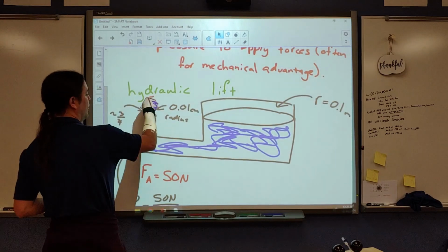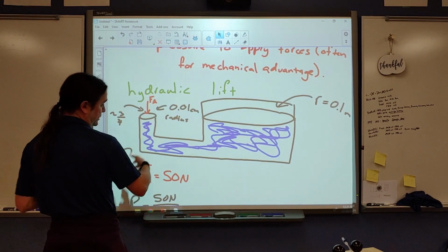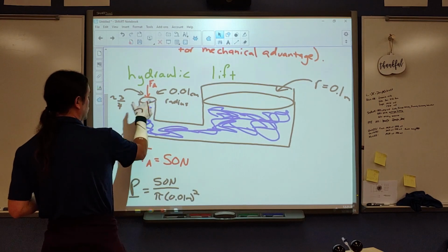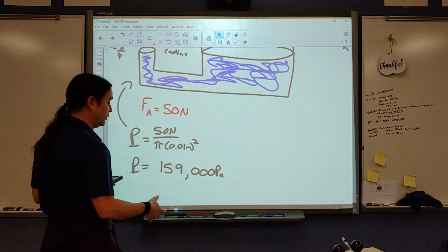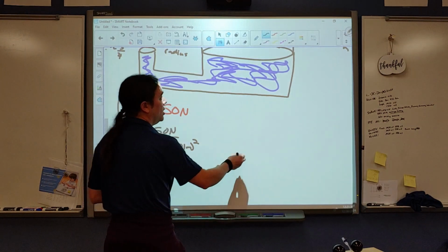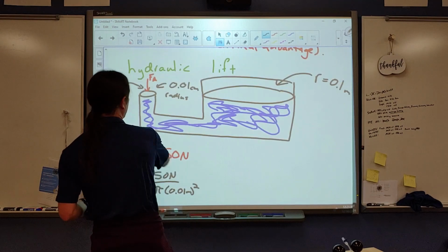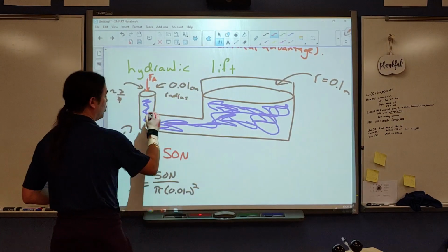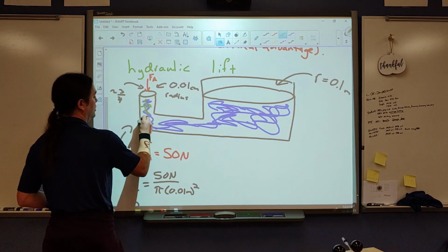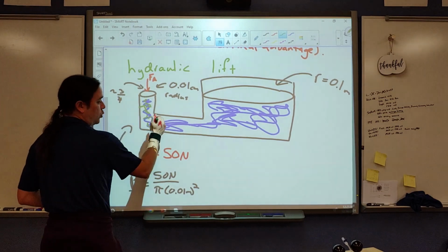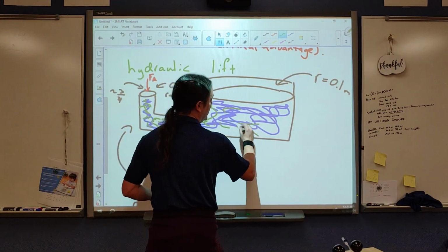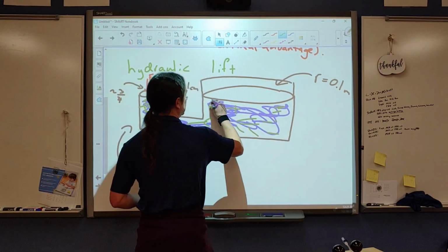So, interesting that I'm only pushing with about, like I said, maybe a little bit more than 10 pounds of force. But we've got such a small area that even that relatively small force can result in a large pressure. Okay, coming over here. This pressure is then distributed throughout the fluid. So the pressure increases here. We're squeezing the entire thing. So the pressure throughout the entire fluid is actually increased by this amount.